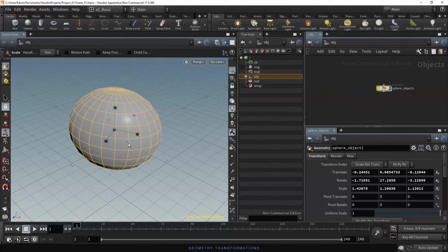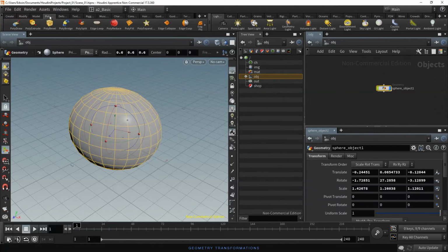In the operation controls, we have lost our sphere parameters. To show them again, first select the object. To do this, use the black arrow in the selection tool on the toolbox. Click on the object and press Enter. There you are. Now, let's subdivide this geometry.